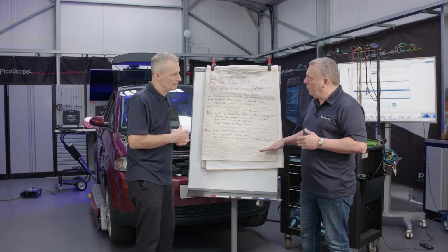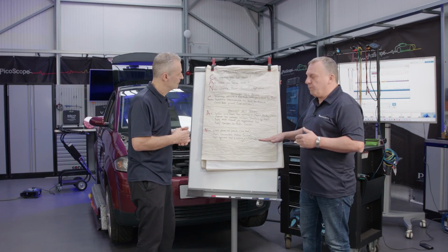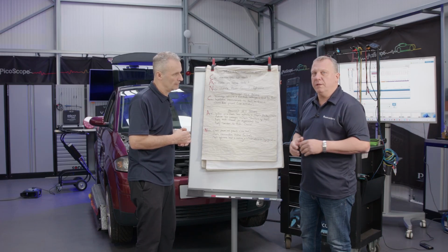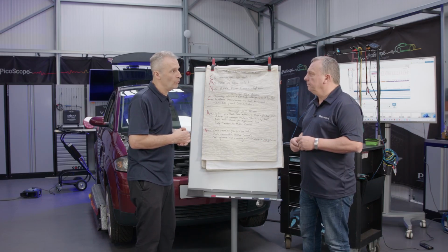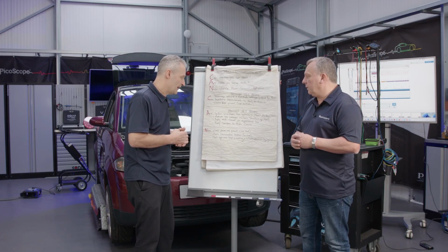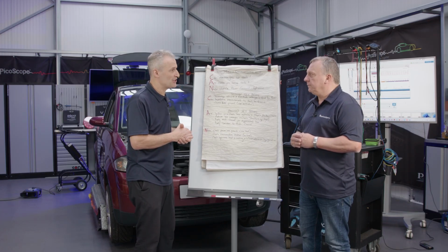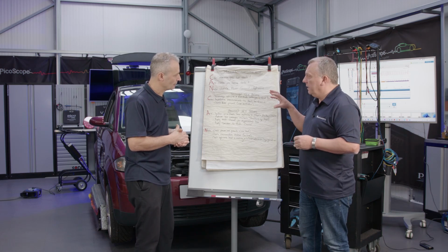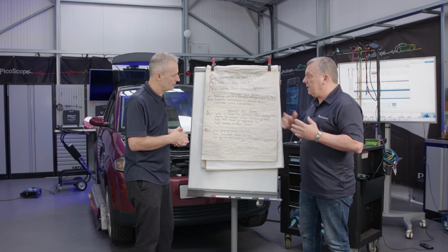But if you've done all of that above that, you're probably left with software or configuration or coding as possibly the error. Or worst case scenario, yeah, the ECU itself. It could be. Yeah, it could always be. Reluctant to just go for ECU because there's so much to do. You have to rule everything else out, and that is quite a comprehensive way of checking any network.